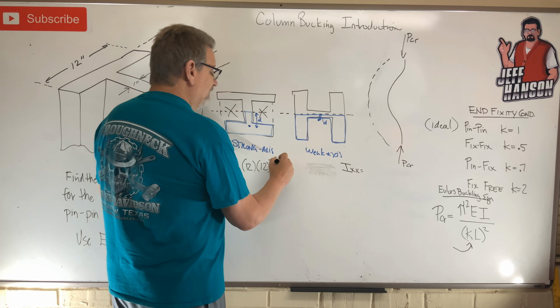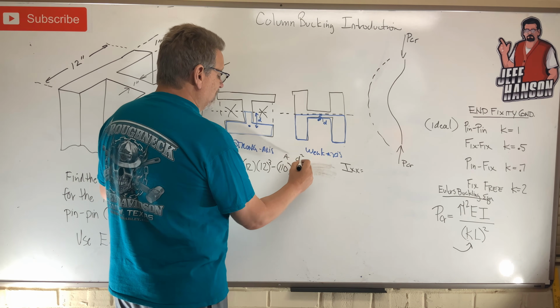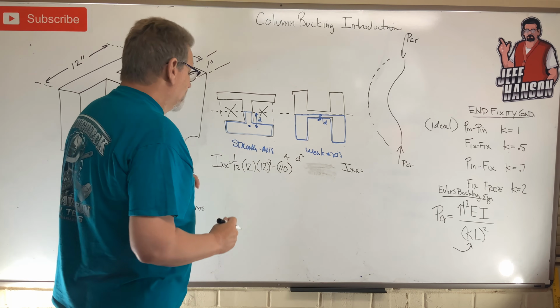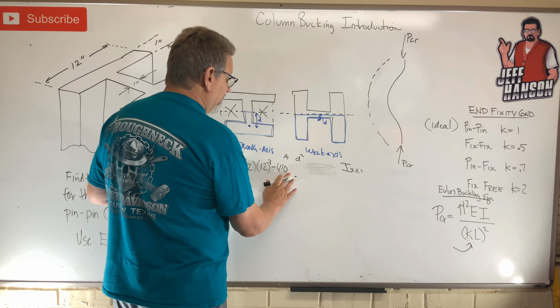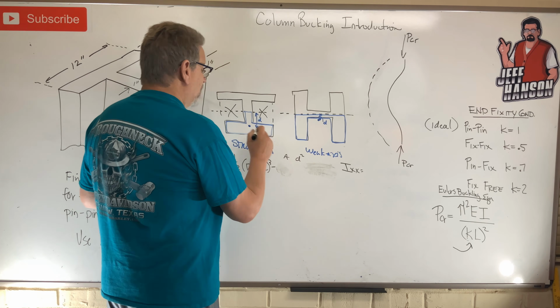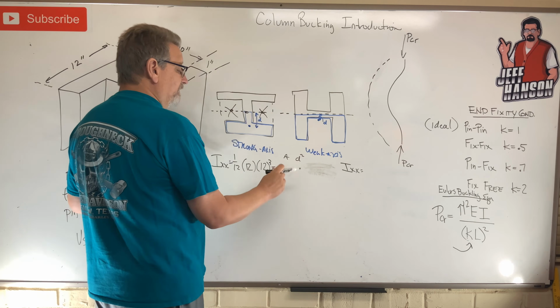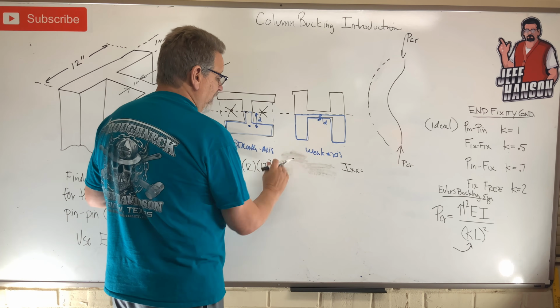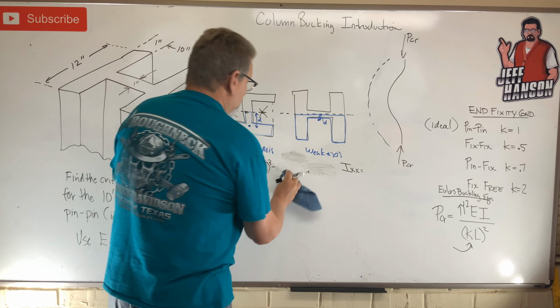What are you doing? This is A D squared. Remember the parallel axis theorem? A D squared. No, no parallel axis theorem this time, because where's the centroid of these pieces? The windows, the centroid is on the axis, so D is 0, isn't it? So we don't need the parallel axis theorem. We got smudges.